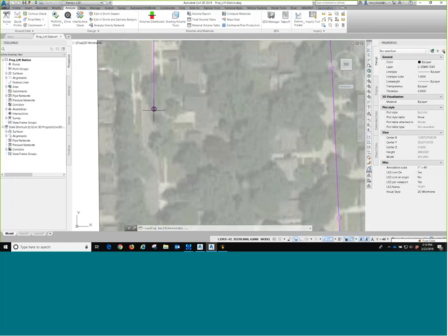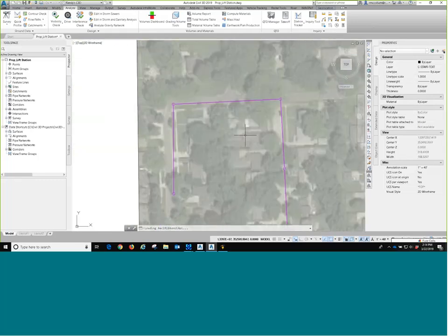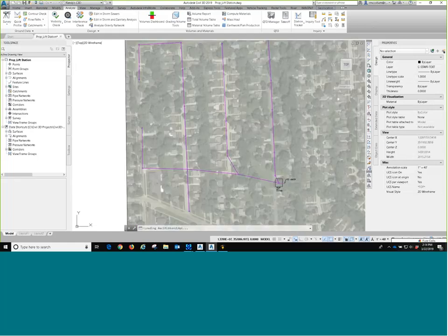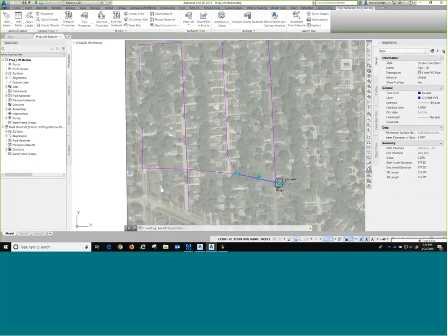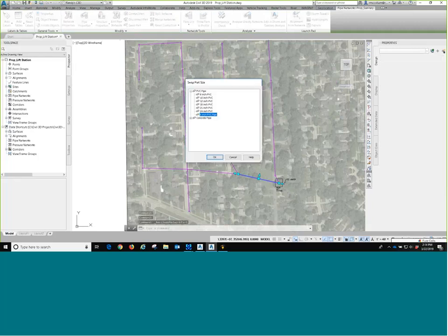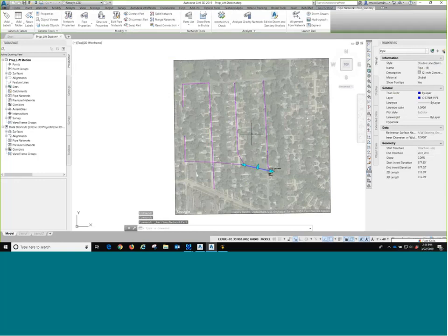And it put in no sumps, because I am assuming that each one of these junctions has a formed channel in it, and I don't want water to pool in those. So I set it up right now all 12-inch concrete, actually, except for this one. Before I mess this up, I'm going to swap this out with an actual 12-inch concrete so I don't get any surprises.